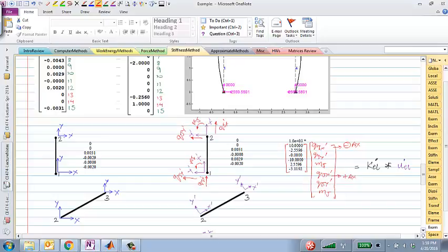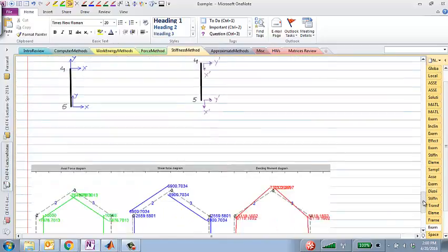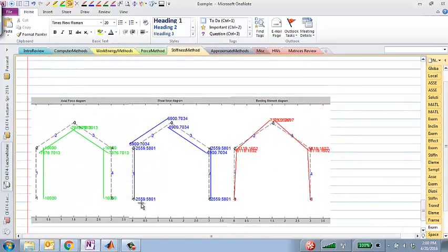J prime is right here. That's negative shear force, and that's positive shear force. So let's check again. The second element is minus 2.56. The fifth element, Qjy prime, is plus 2.56. So indeed, if I take positive of the second element, negative of the fifth element, I get a shear force in this member that's negative 2.56 kips or kilo units.